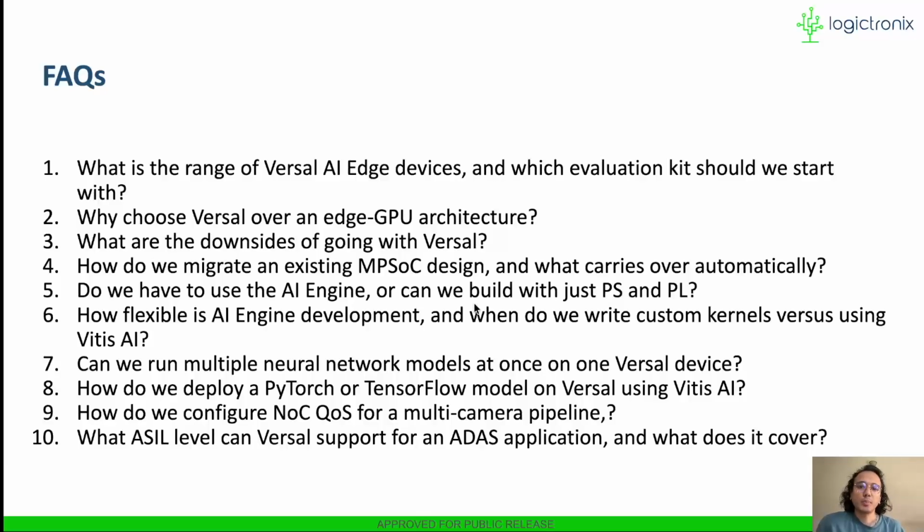On the topic of whether to use Vitis AI or create a custom kernel, if the CNN networks or neural networks that you are currently using are supported in Vitis AI, it will be much faster to directly use Vitis AI. Also, if the performance and latency requirements are fulfilled, then Vitis AI is preferred. But in the case you have a custom network and the performance is not fulfilled by Vitis AI or the NPU, then in that scenario AI engine kernels can be custom written for that neural network.